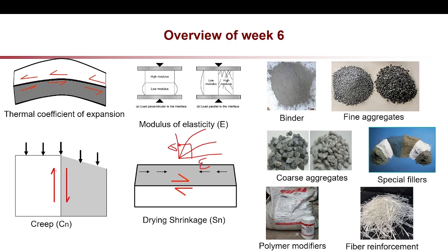Whenever we are applying a repair material, we are assuming that the substrate material, the old material, has already experienced the creep, the service creep, which it has to experience over the whole service life. When we use the repair material, it will experience some creep, and because of this creep, there are chances that the shear bond between these two materials will break.